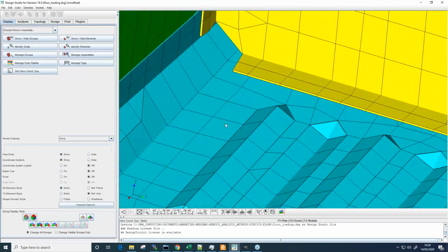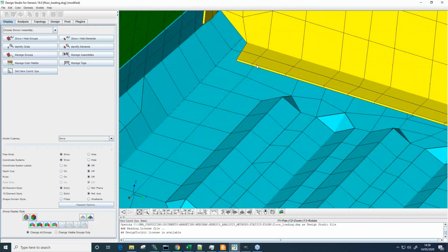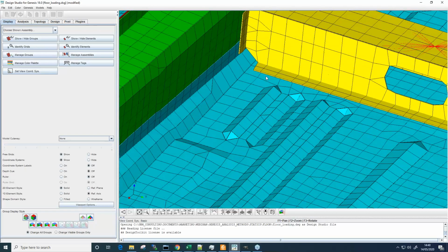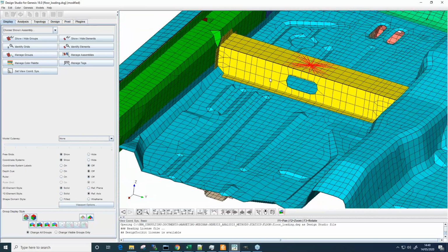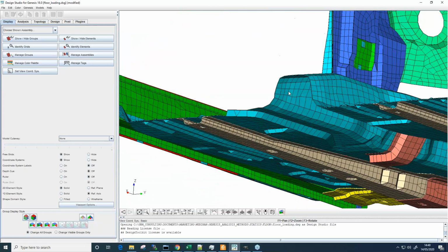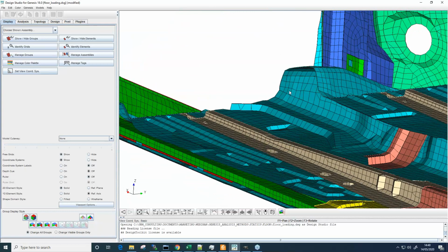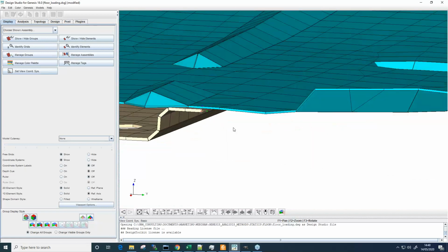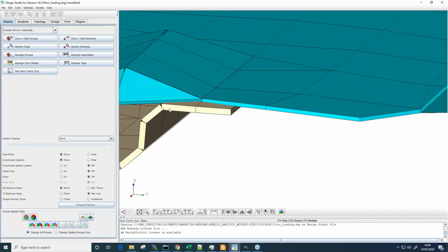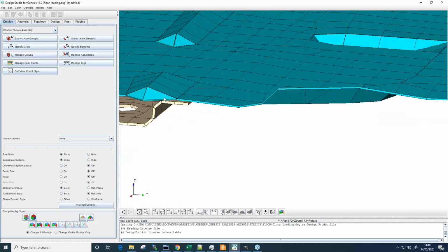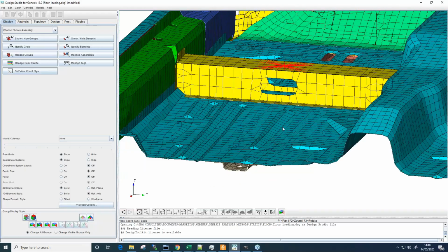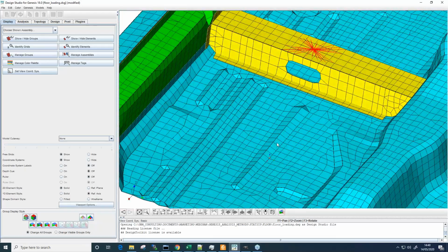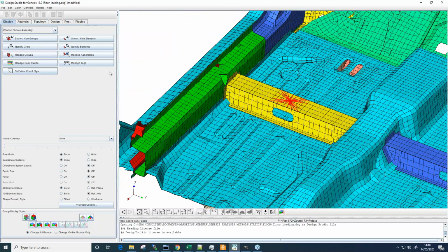So in this particular case, you can see we've got quite thin parts, so it's less of a significant factor, but still important to remember, particularly if you want to consider gaps and distances in detail and the effect of those gaps. Okay, so you can see here these parts are actually in general not passing through, but we do have some penetration. So what we will do in this example is take advantage of the ignore contact type.